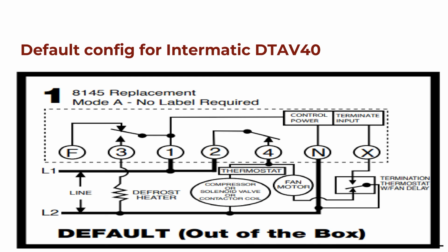But this being a thermostat, it's not going to return back to its other contact point right away, will it? There'll be a natural time delay with that. As the compressor turns on and starts pushing cold refrigerant through the evaporator, this sensor is going to move back in the opposite direction. Once it hits its opposite set point, it will close again and then turn power onto the fan.